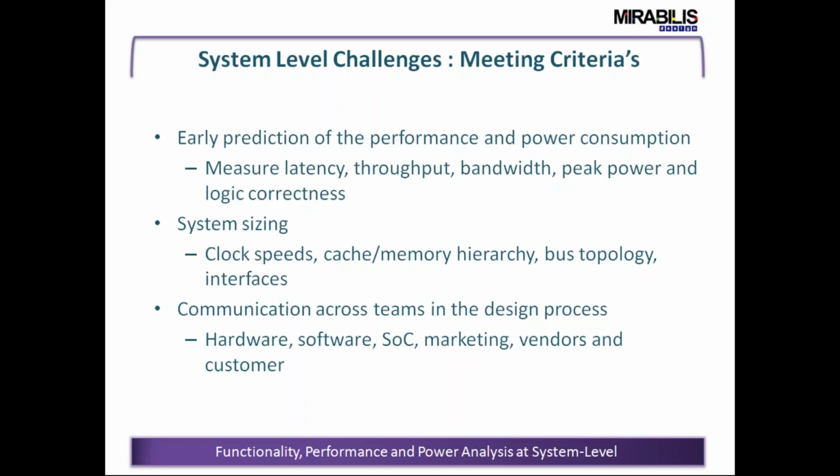And in addition to that, you may have to select the right system components as well. So you'll have to make sure that the components are running at the optimal clock frequency, and the cache or memory hierarchy is correct, or the bus topology, how you have defined your algorithm for the bus select. And these are the kind of problems that go along with the selection of your interconnect as well.